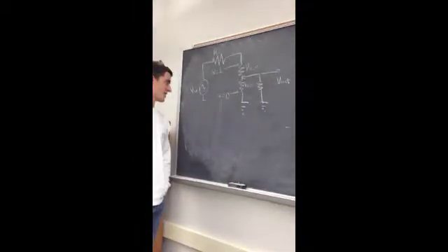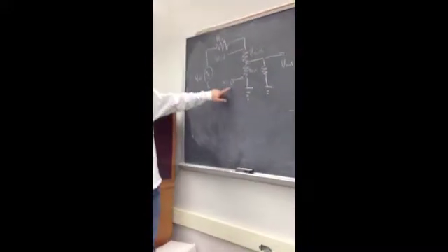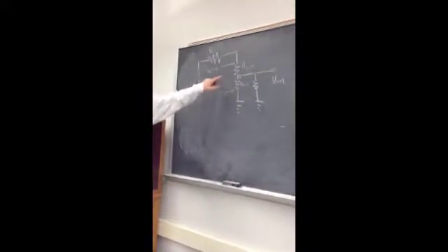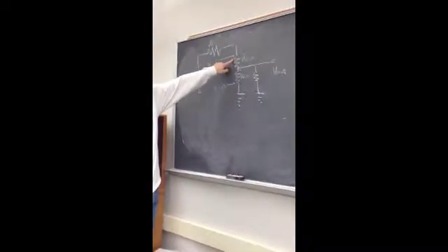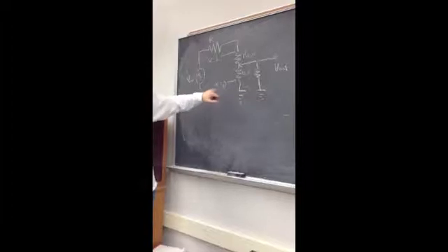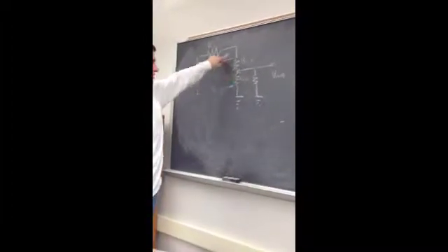The potentiometer has alpha values of 0 to 1, with 1 being set to the full resistance, in this case 108 kiloohms, and 0 being set to no resistance, and it varies linearly across that relationship.